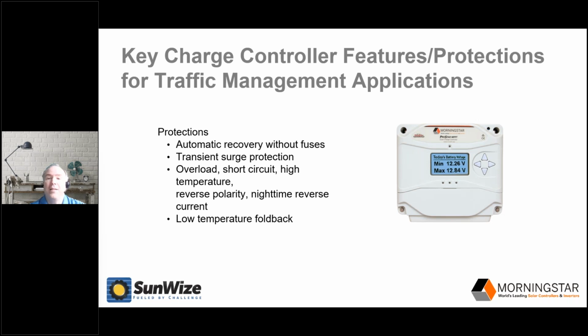And if you're using lithium batteries in a potentially cold environment, you might consider a controller that has a low temperature fallback provision, which decreases and eliminates charging when battery temperatures reduce to levels that can result in damage to batteries. All right, so let's go ahead to the next slide.